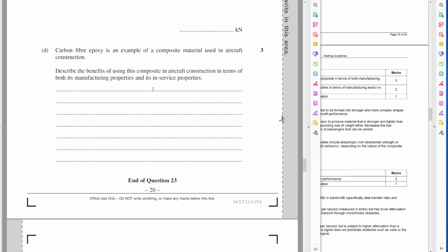So here's the answer I would give. First of all, let's do the E, which is to elaborate, right? So we're going to have 2 points. The first point is going to be manufacturing. So we're going to say, well, how do we manufacture aircraft components? We have 2 ways of manufacturing CFRP. We can either use hand layup or vacuum layup. For planes, we're using vacuum layup. We're using autoclaves. We're using high quality materials.